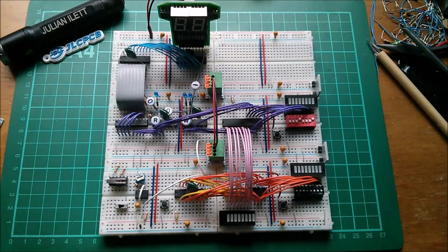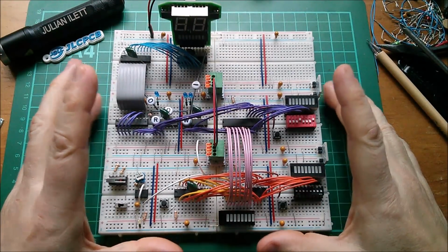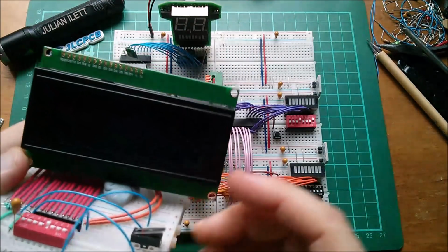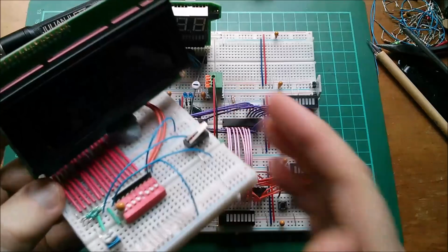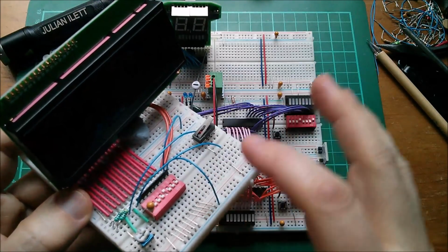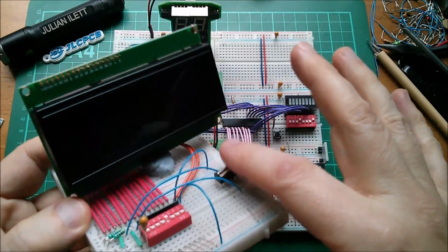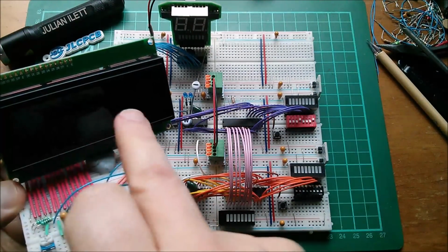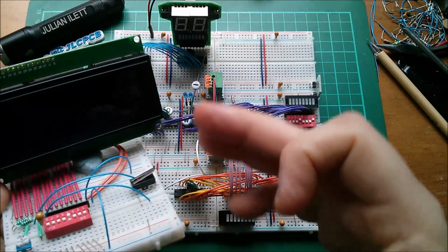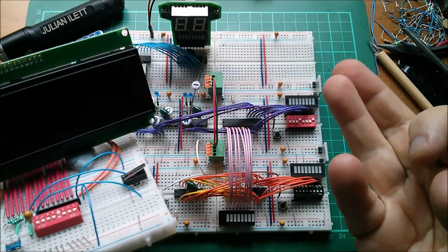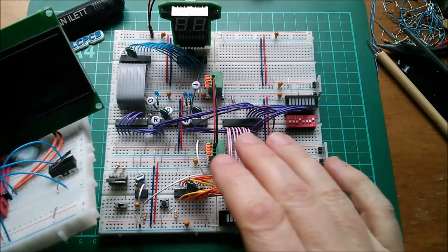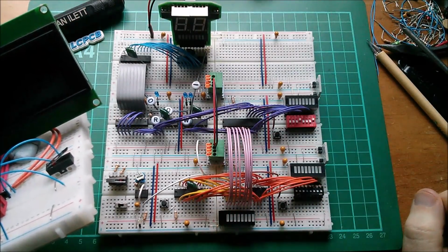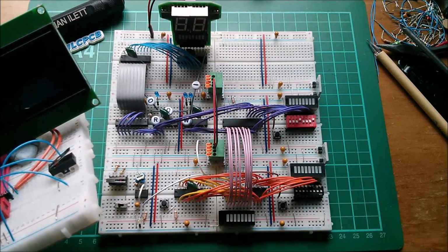Good morning all. Today I want to put something on my 8-bit breadboard computer, and it is the LCD. Now that's currently on this breadboard where I just manually put commands in and sent them to the display. What I want to do now is try and write a message on this display. Maybe one that cycles round so that you can see it's doing something, and program all the sequence steps into the RAMs on my one instruction computer.